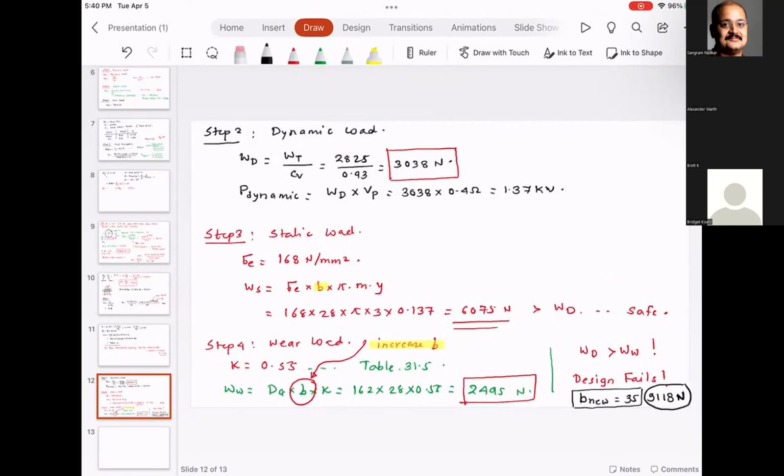And this wear load tells you the maximum load that the contact surface can resist before there is pitting. Before that, there is small material removal. If you look at a used gear, you will see some tiny dots on the surface. Those dots are because of the pitting, which takes out microscopic material, and gradually that deepens, and then crack initiation starts where those pits are.